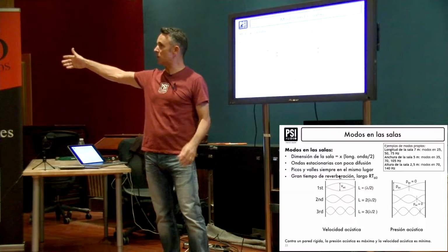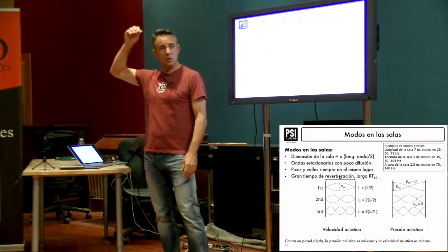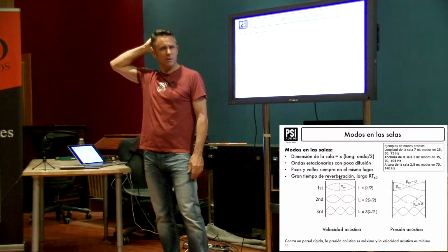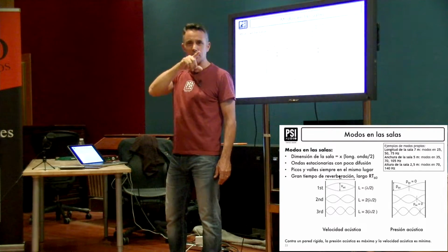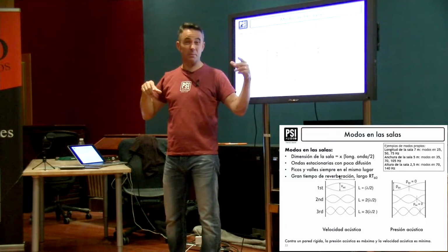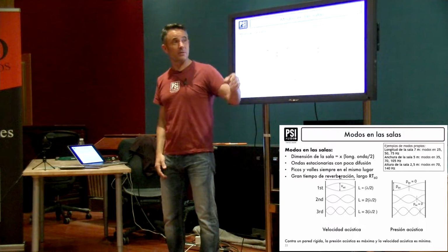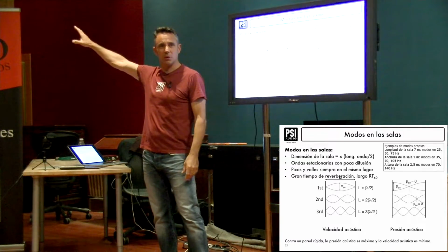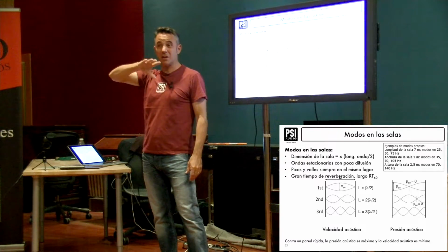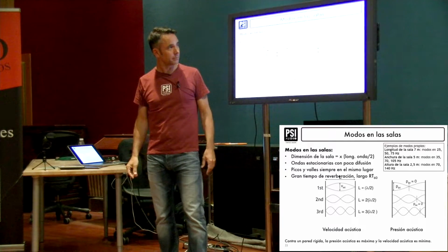In a mode here, this is probably 10 meters long, so that's 35 hertz. So 35 hertz is the second mode. The first one will be about 17 hertz. So you'll have high pressure here, and go down, and high pressure over there again. So they're very long wavelengths. Anyway,